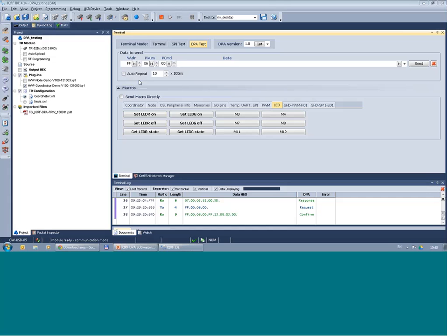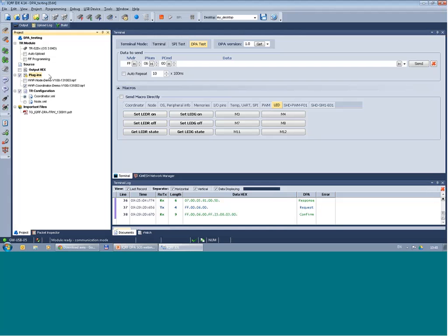So what are the first steps? As we said, you download the plugins, the demo hardware profile. As you can see, you have a hardware profile for the nodes, and you have a hardware profile for the coordinator. Those plugins you will upload just by pushing F5 into the specific modules, so one coordinator and then certain nodes. Another thing that you need to do is to set up the configuration of the module.